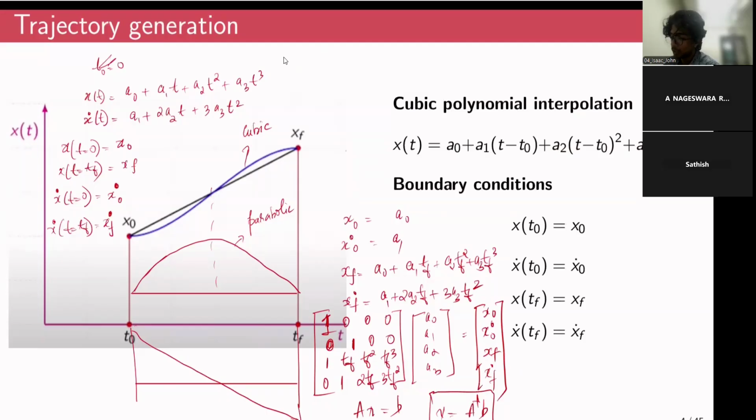Depending upon your boundary conditions, you can have zero velocities at the initial and final ends, or you can have non-zero velocities. But then here you can see at time t equal to 0, you will have a sudden acceleration. It's not infinite, but there is a sudden jump. It gradually drops, and it will be 0 at the midpoint, where the velocity is more or less at its peak.